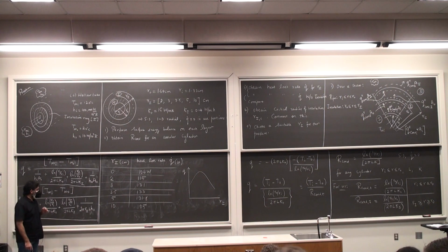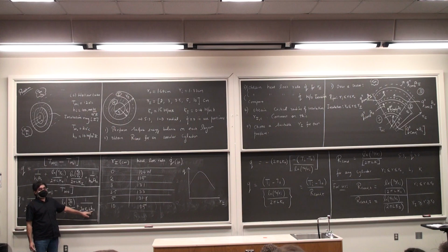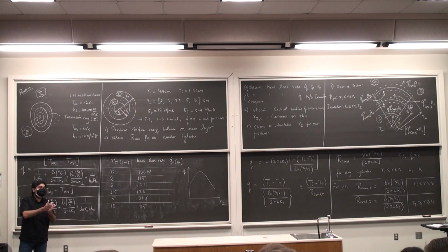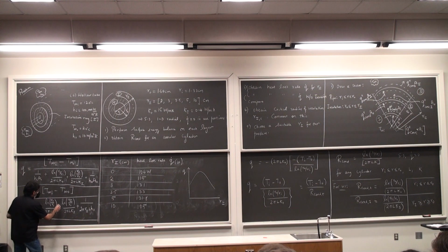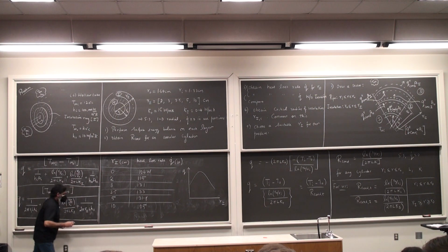In some sense, it is also dependent on the ambient temperature, as one of you asked. Is it dependent on the ambient temperature? It is dependent on the convection coefficient, then, which is a function of the ambient temperature to a small extent. It's a weak function of the ambient temperature, but it's a much stronger function of what's happening at the boundary between the insulation and the outside. Okay, so the two things, and maybe I should talk about this very quickly.